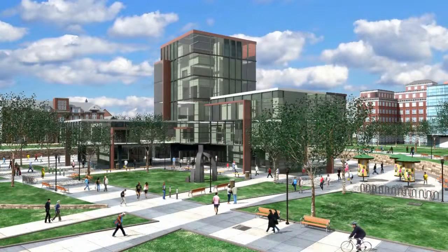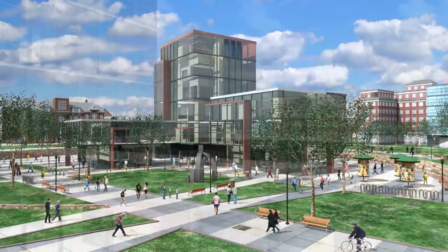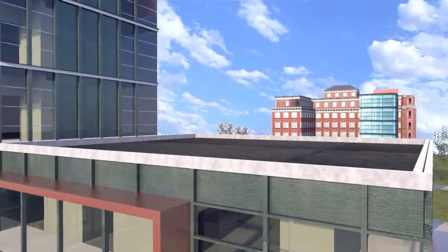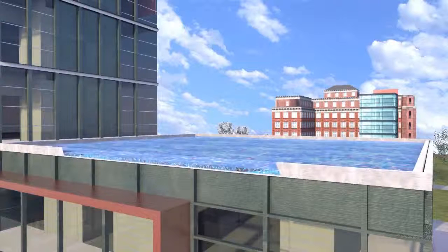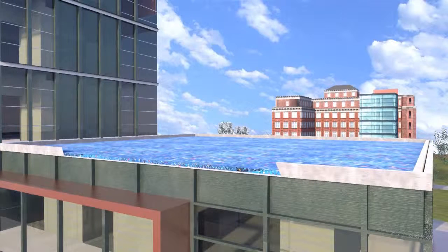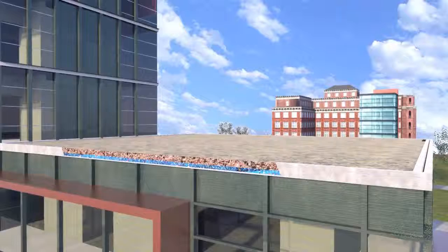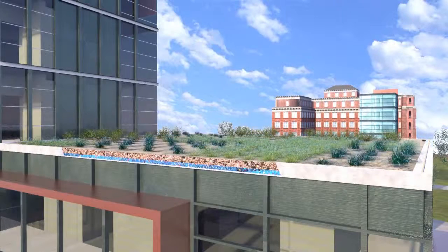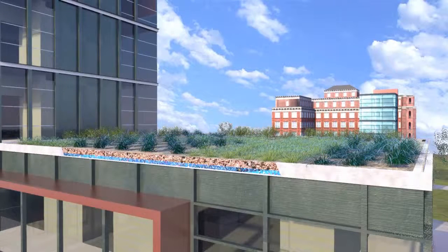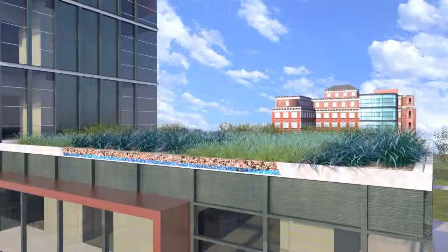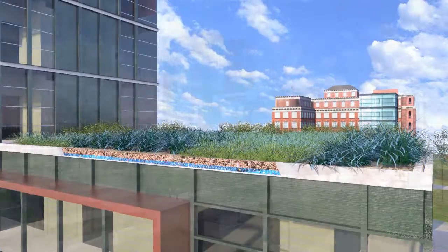There are more effective means to manage stormwater using sustainable systems and materials that prevent flooding and replenish the aquifer. The first system is a green roof placed on top of a building. The green roof is layered with drainage materials, compost or planting soils, and vegetation. The green roof can absorb some of the rainfall, reducing the amount of water flowing into the storm drains.